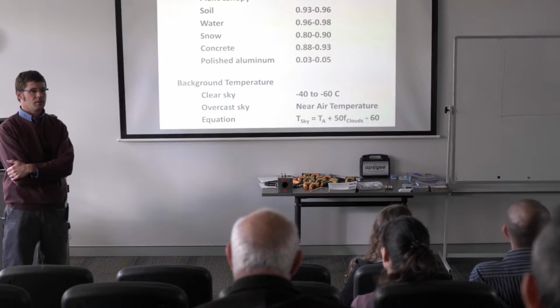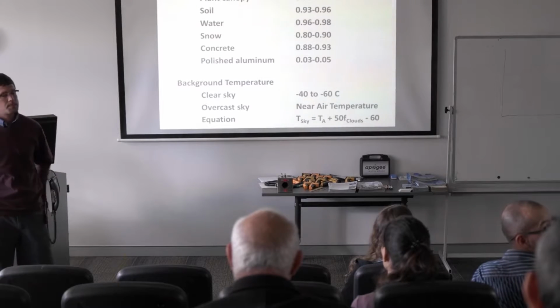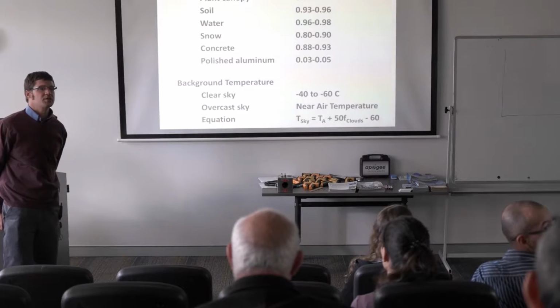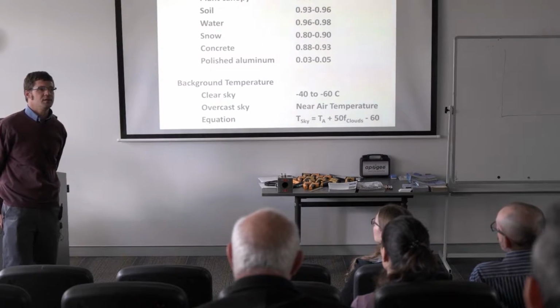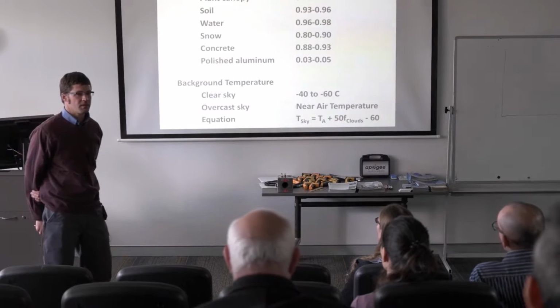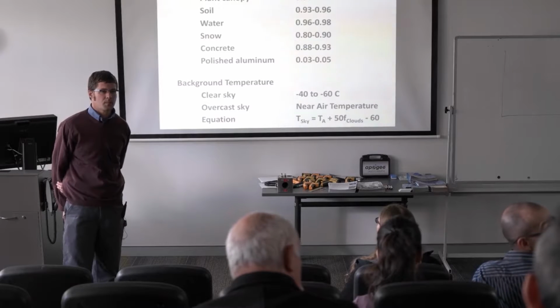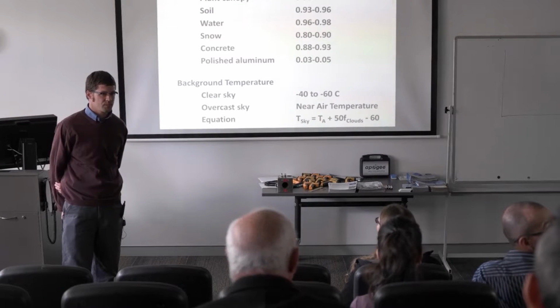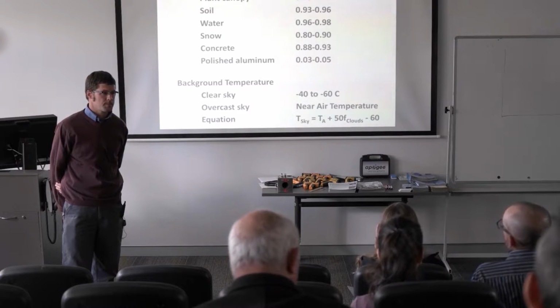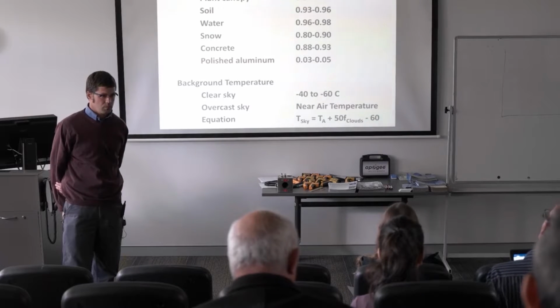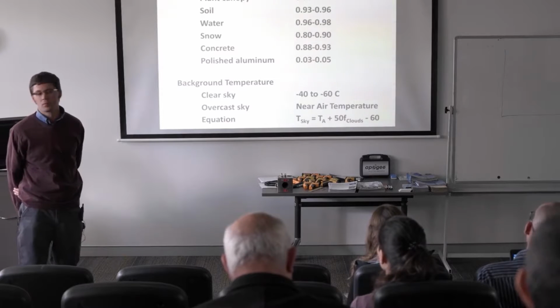What they do is take the reading and multiply it by the emissivity. Actually, they divide by the emissivity. Or divide. Right. But it often makes the measurement worse instead of better, because they're not including the reflected radiation that Mark's talking about. So, boy, does that confuse a lot of people.